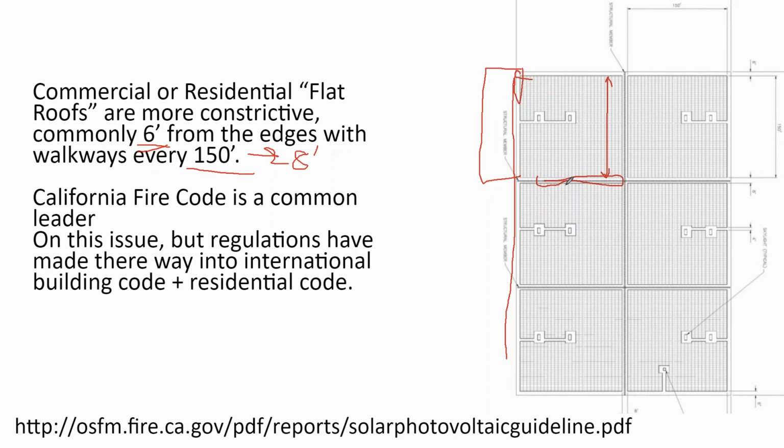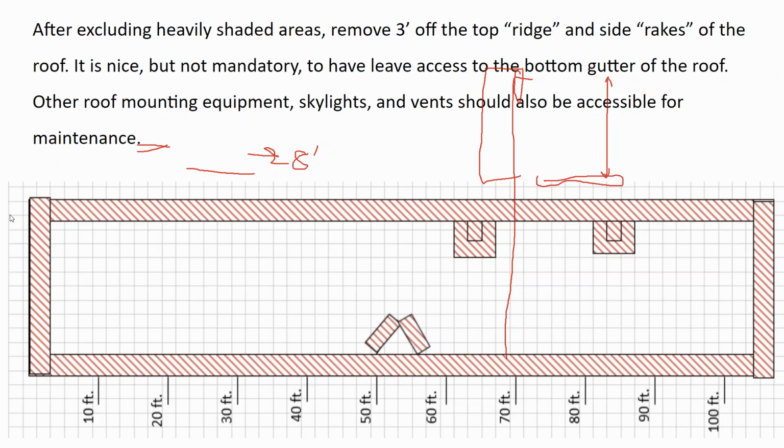So as a designer, I'd say just don't push every single constraint in the name of filling up all the space possible. While in general you want to fill up all the available space, there's some nuance in circuit design, circuit layout, racking layout, ease of installation and servicing that should also be considered, particularly if you're going for a lower cost-effective project budget.